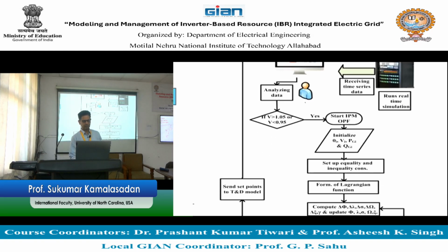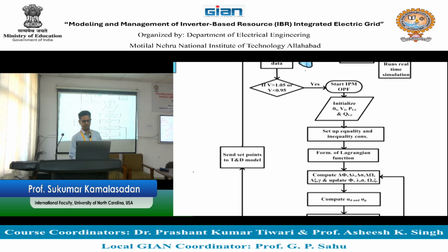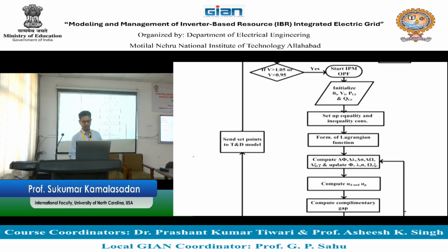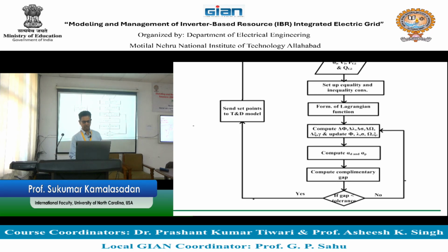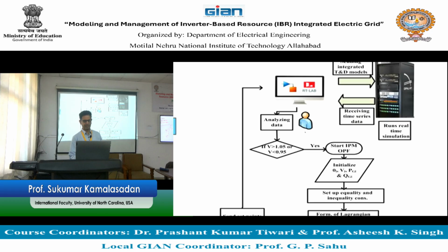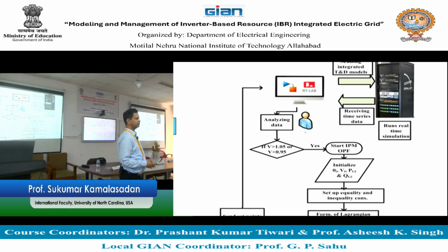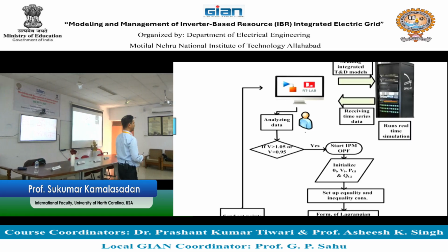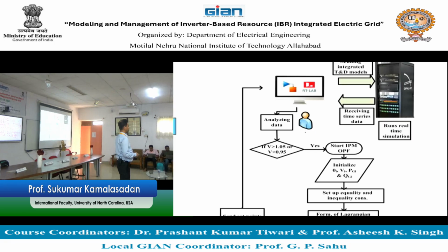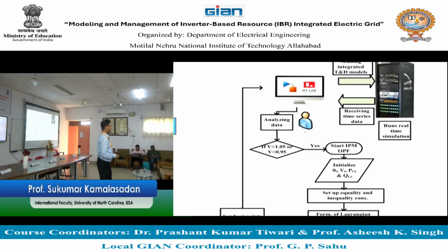So you can actually get the data, analyze the voltage profile, develop an OPF, compute the OPF, get the output set points, and those set points can be sent to the models for controlling the power and the voltage. So this is an example of integrated T&D analysis for control.